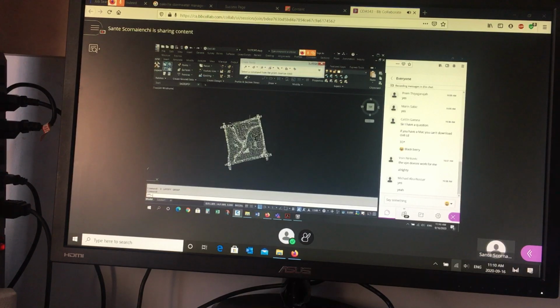If your description is edge of pavement, I want to put that on a layer called edge of pavement. If your description is tree, I want to put you on a layer called tree. And then you can isolate the various layers and start looking at patterns and how things are set up. When they're all on one layer, it's not a very useful setting.